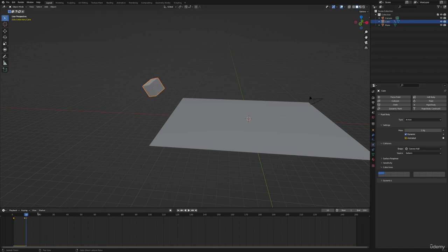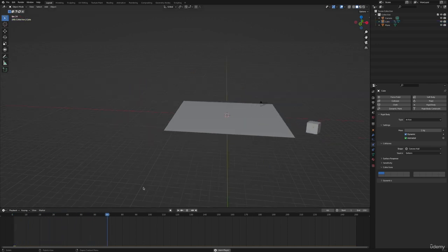So first we uncheck the box, and then we press I to make a new keyframe. This is very important because then the keyframe will actually register you unchecking the box. Now, once we've done that, you can see that we now have a pretty good dice animation. It is rolling a bit too far now, but that has something to do with the friction.